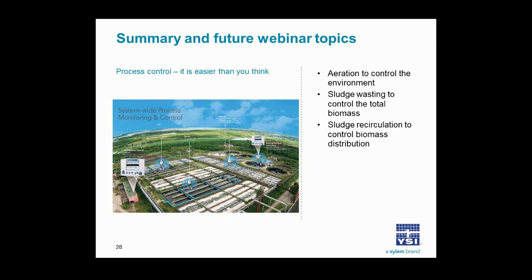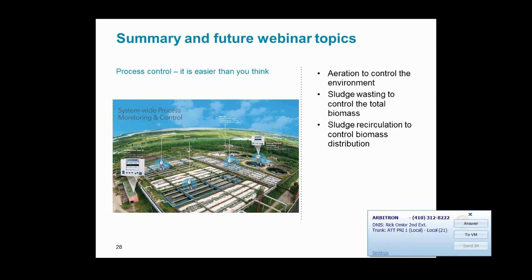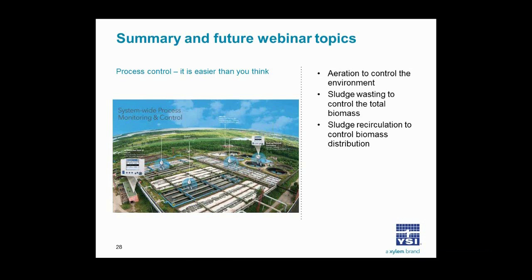By, for example, not controlling SRT, the sludge quality, the properties of the biomass, can vary. For example, the settleability, flocculation rate, compaction rate. By maintaining an SRT, you find an SRT that works, and you keep your system at that SRT to keep it functioning properly.